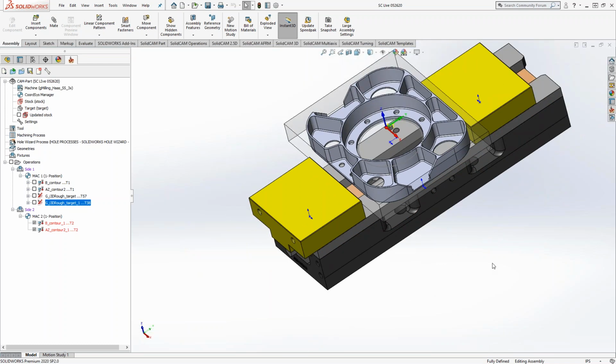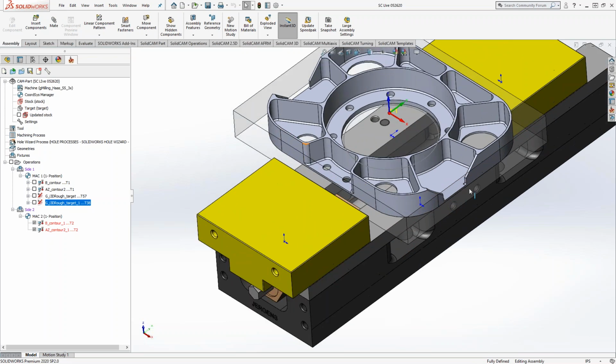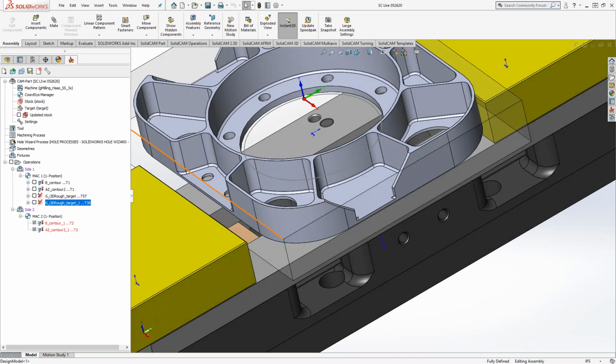But we were talking yesterday about the different packages. So if you had the 3D package, you could use 3D iMachining. In this case, if I only had 2D, I could do something very similar. You still get the multi-tool functionality in 2D iMachining, and you get the same ability to set up separate working areas. So really the only difference between 2D iMachining and 3D is the fact that the 3D can do this taper, and it can do a lot of recognition of some other stuff that 3D and 2D have differences in. But mainly, it's that one 3D feature.